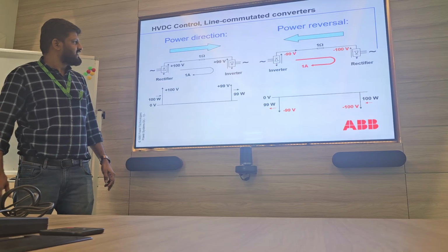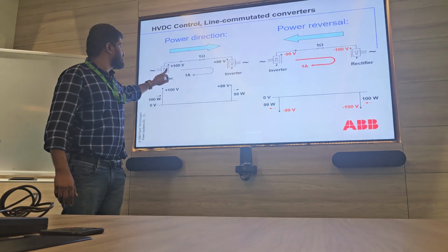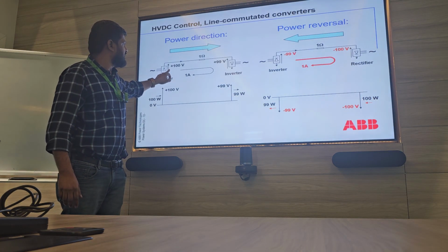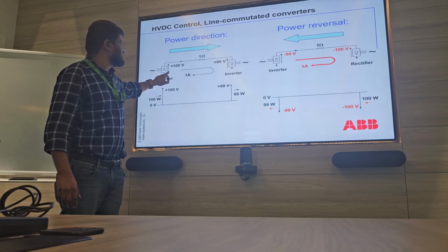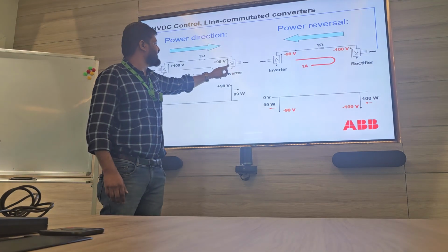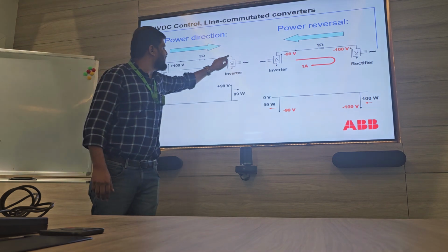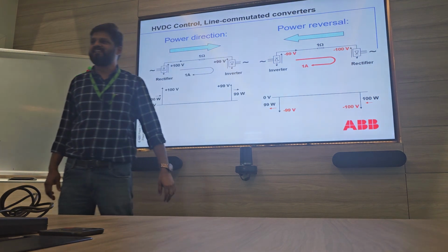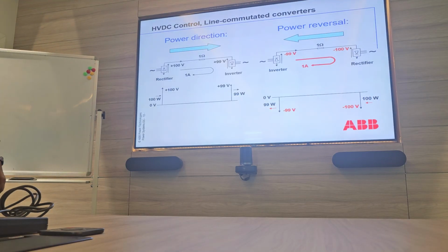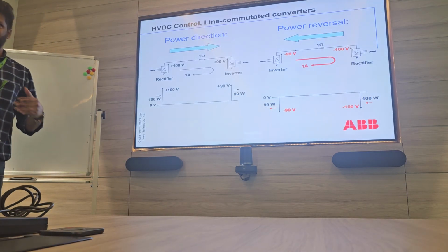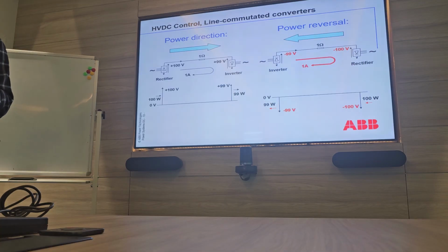How about the second one, the other inverter side? Oh, this is a mistake. Yes, this is a mistake. It has to flow like the other one. But you know, the thyristor is a unidirectional current device. We can't change the current direction through the thyristor, we can only change the polarity. It's similar to a diode. It's unidirectional only, kind of like a conductor, one way. Yes.